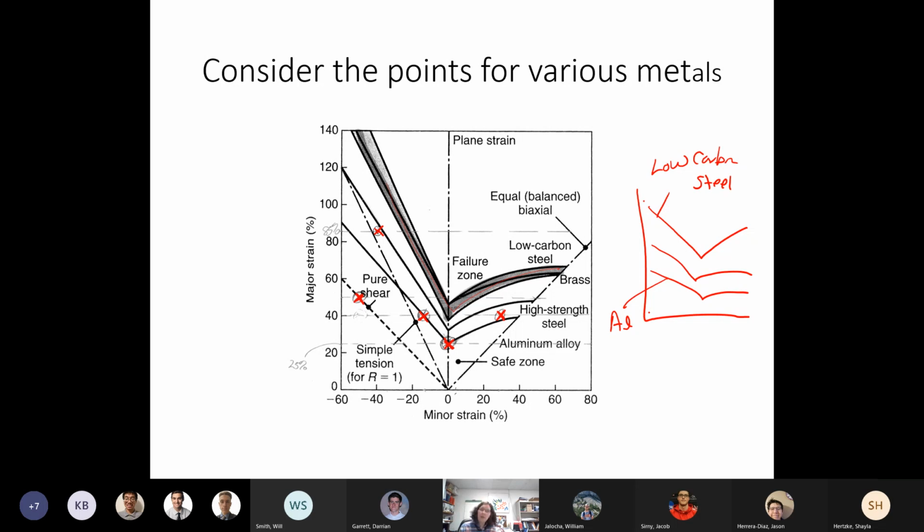And that is the case. There are some challenges with aluminum. We know that aluminum has a high specific strength, meaning its strength to weight, but the modulus of aluminum is a third of that of steel. So you have some challenges there.